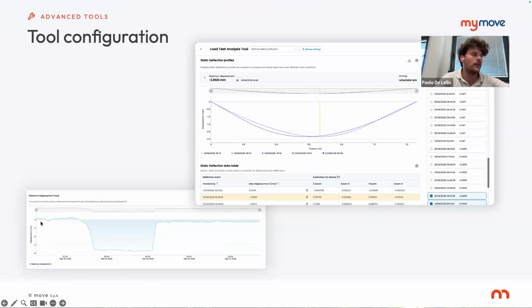And for example, you can see here that you have three different phases: one before the load of the beam or the span in general, the phase of load directly, with the maximum result that you can read here. And after, you can understand if the deflection and the maximum value return to the normal and initial value, or has a residual displacement like in this case.